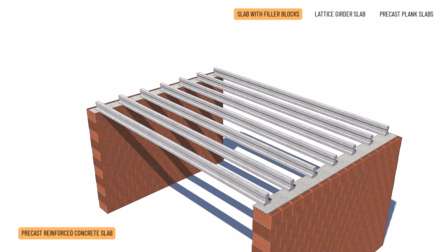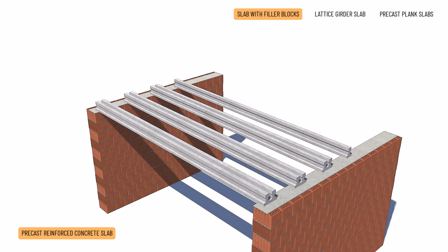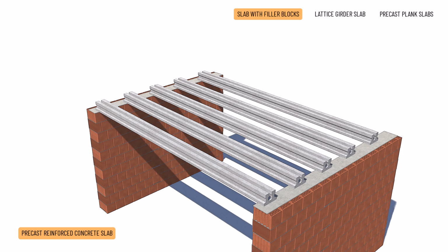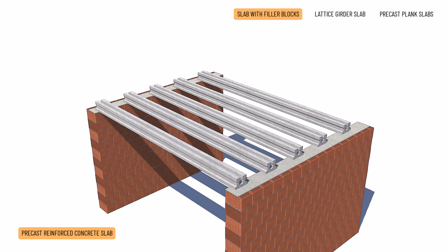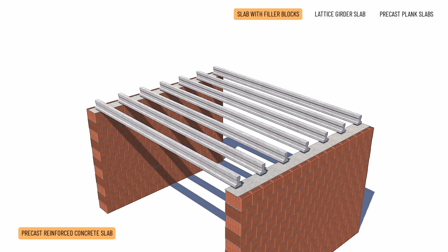Above a certain span, the beams need to be doubled, increasing the load-bearing capacity and reducing deflection. To achieve less deflection and fewer cracks, it is recommended to use a system with pre-stressed beams. Important: pre-stressed beams must not be cut, as this would release the tension and compromise their structural integrity.